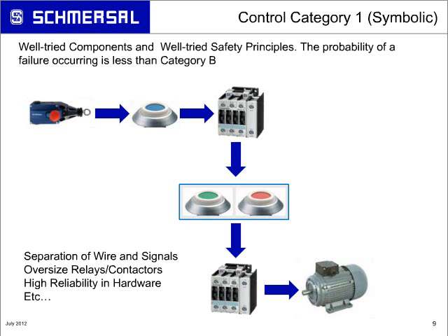Well, you haven't eliminated the possibility of short circuits from occurring or significantly reduced them. So one of the methodologies is you run the cables in separate paths. So you have your feed wire running to one side of the switch and a return wire routing down another side of the machine into another spot in the control cabinet.